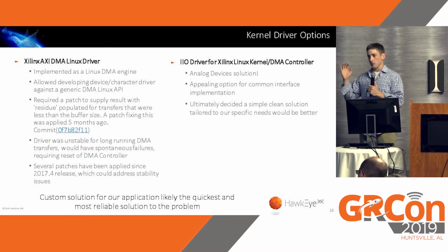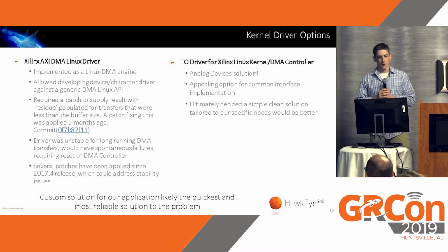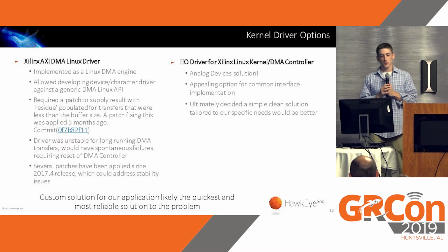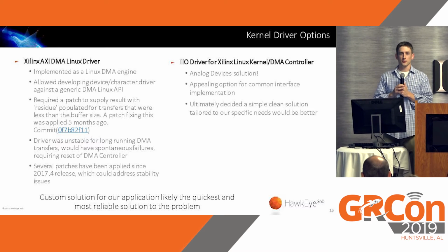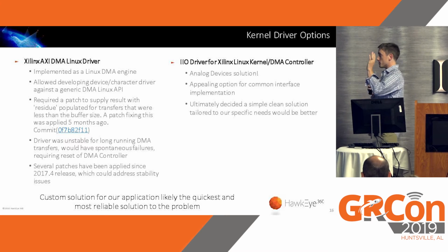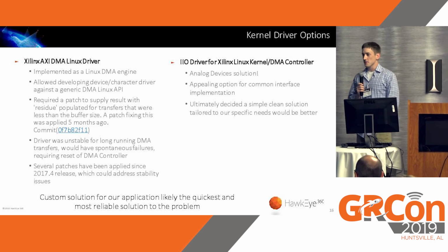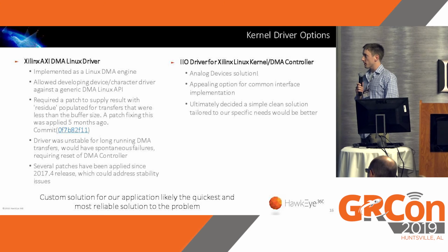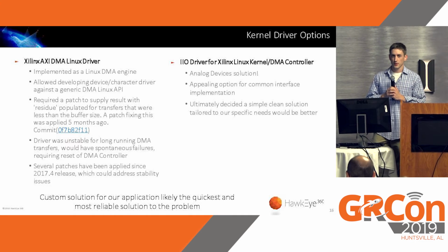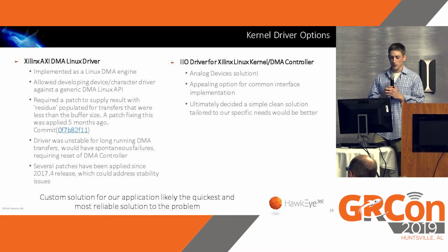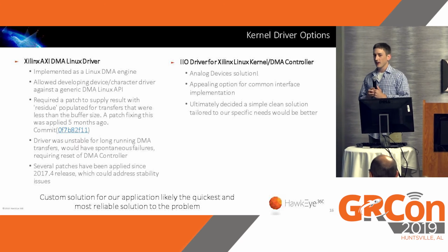Okay, moving up the stack. We've talked about FPGA, now let's talk about the kernel driver. We started off trying to work with the Xilinx AXI DMA Linux driver. There's a long story with that one. I won't go through each individual point, but at the end of the day, we weren't able to get it to work in any reliable way. We even tried adding upstreaming patches for this, and it was still unreliable with lockups. And so now, maybe in 2019 it's better, but we haven't actually returned to that one.